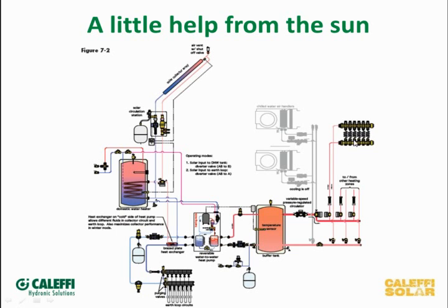Going to the heating mode, again a manifold distribution system here going out to your radiant or panel radiators, whatever that might be. Multi-zone, so it's important again that we have a way to regulate the flow to that. We've shown in all these here a pressure-regulated delta P pump. We think that's the way the industry's going. Certainly if you choose to use a regular fixed-speed pump, you would want to put a pressure-activated bypass on the end of these manifolds somewhere in the piping system so that as zones start shutting off, you would just shed some of that pump head through the bypass valve instead of using the pump that can automatically do that by reducing its output by changing its speed. I don't know if I mentioned that early on or not, but what else on this drawing? I think I've covered everything on that.